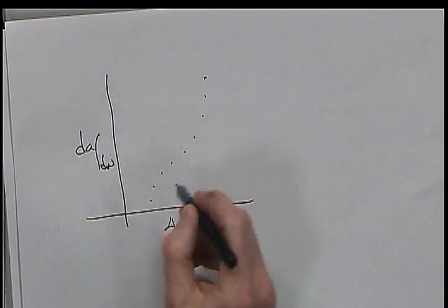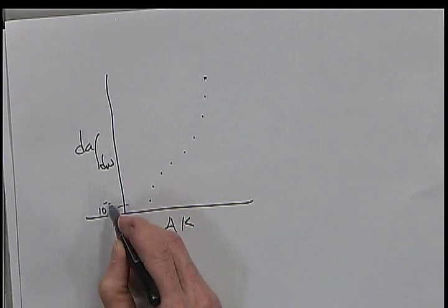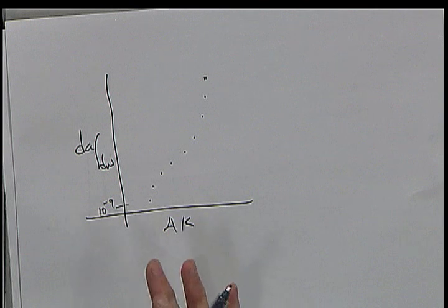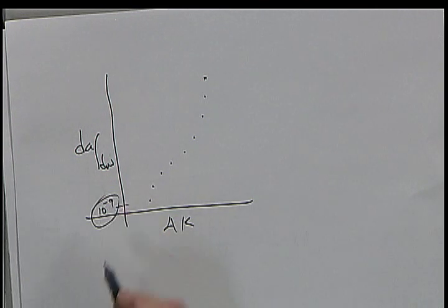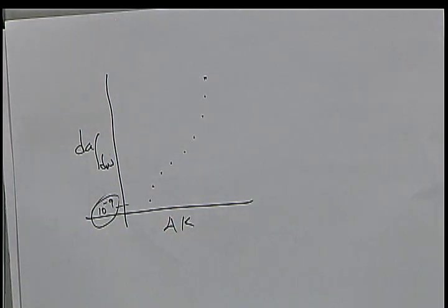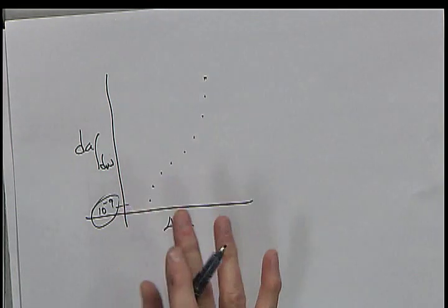Well, imagine that if we're down here at 10 to the minus 9 inches, I always work in English units, I'm not very progressive in that way. If we go 10 to the minus 9 inches per cycle, and if we're running a test at 10 hertz, and let's say that we're trying to measure cracks every 100th of an inch to kind of minimize the amount of scatter, think how many seconds that would take between each data point you would collect, and so how long it would take to do the test. So it's often difficult to get a lot of data in the literature.